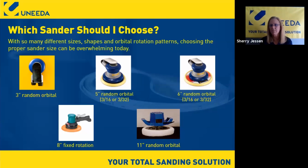6-inch, same random patterns, 3/16, 3/32 swaths. So those two pretty much mirror each other. The biggest advantage with the 6-inch, especially on solid surface, is the size of the backup pad and the ability to cover more ground than the 5-inch. But with the 6-inch on wood, you tend to get more swirls early on. Because of the bigger pad and the bigger swath, you tend to see swirls earlier.